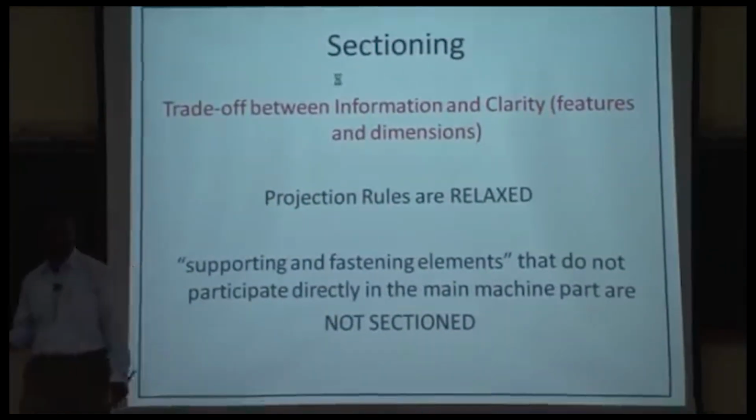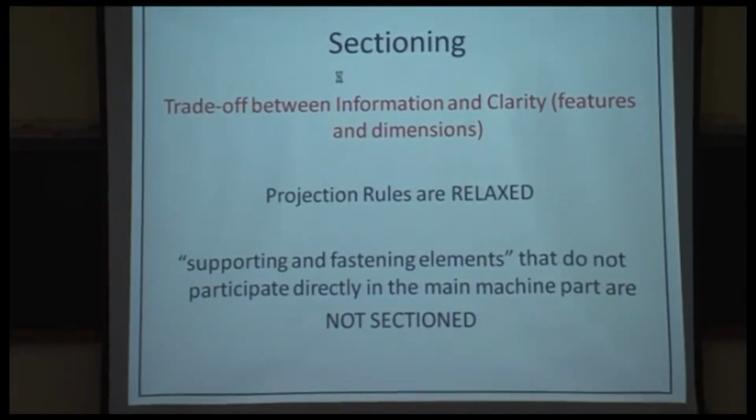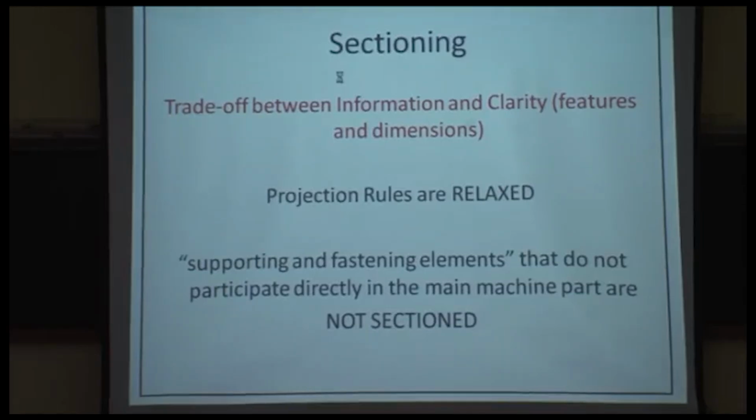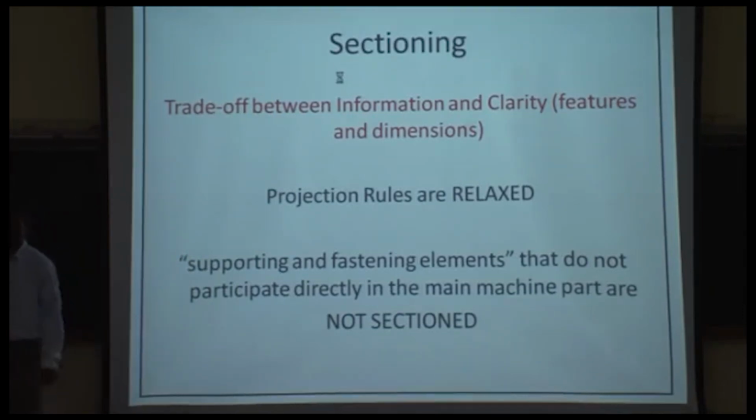Since we are working with orthographic projections, and a section view is in a way an orthographic projection, you need to show true dimensions. Of course, the rules of orthographic projections are relaxed when we are working with sections. We don't have to diligently follow those rules.